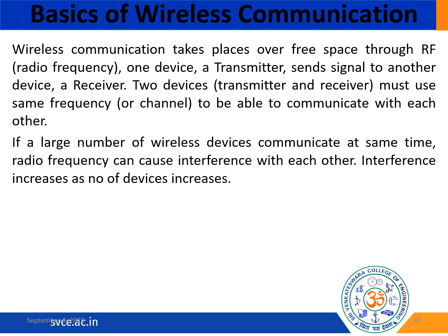As the number of wireless devices operating simultaneously increases, the likelihood of RF interference rises, and it can disrupt signal clarity and reduce communication efficiency, especially in densely populated environments. So effective frequency management and channel allocation has to be done properly. This is essential to minimize interference and maintain reliable wireless communication.